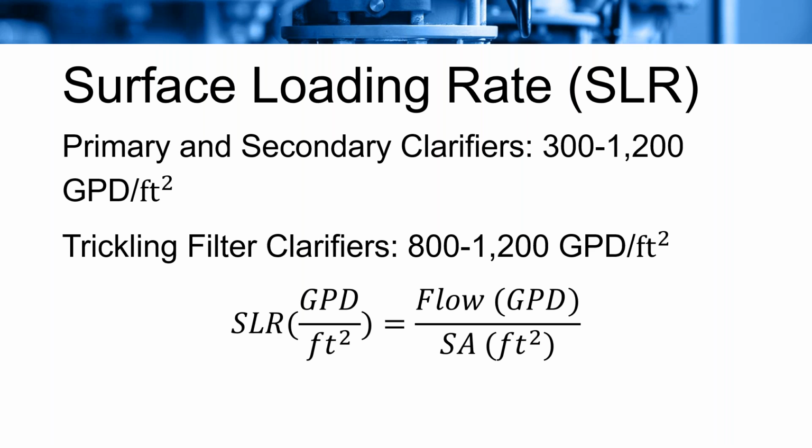And also the lower rates for a surface loading rate will result in longer detention times and can lead to problems associated with that, such as going septic or solids starting to settle too quick. Basically, it's issues with septic. Then you can get some floating solids from that.